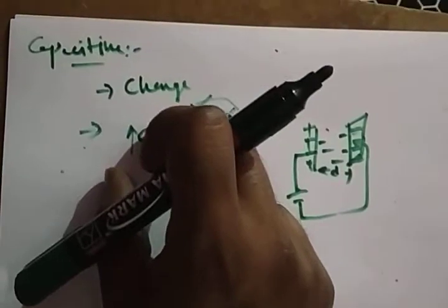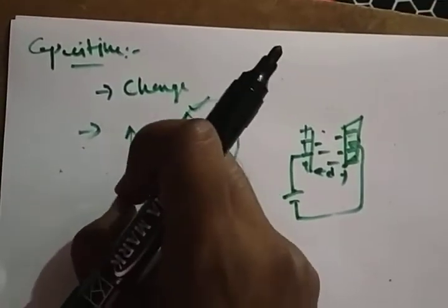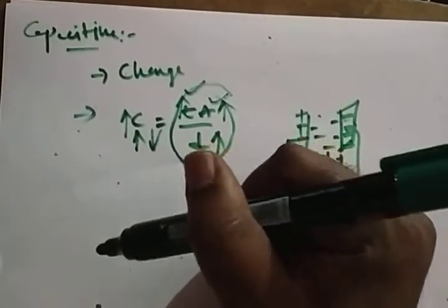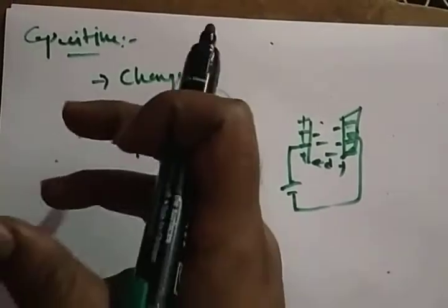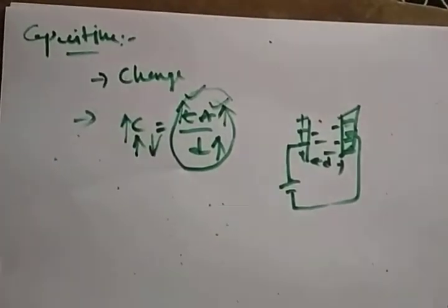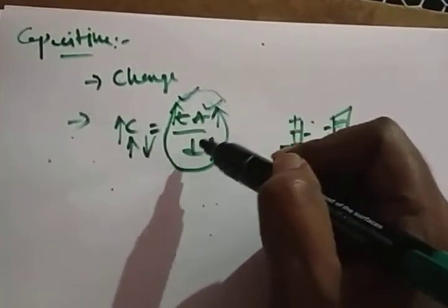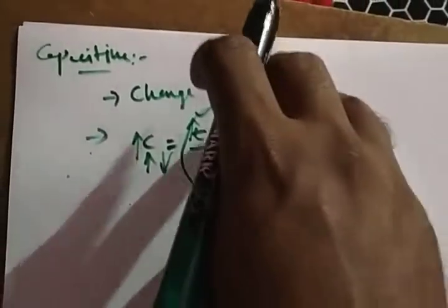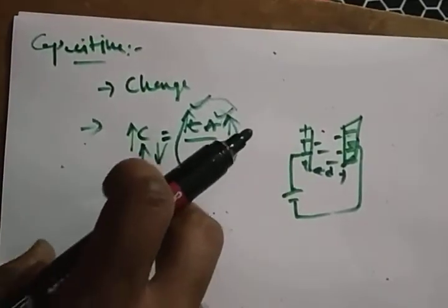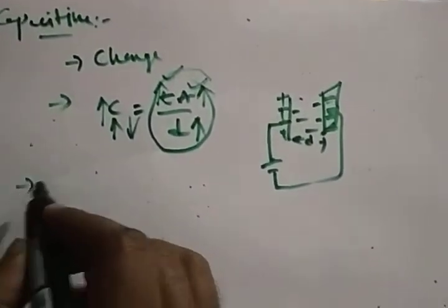You can measure this capacitance with a standard electrical meter, a voltmeter, a Wheatstone bridge, or whatever it may be. You can measure that change in capacitance with the help of that standard meter. The result you get will be analogous to the area, the distance, or the dielectric permittivity, that is, these non-electrical quantities are converted to the corresponding electrical quantity. That's it.